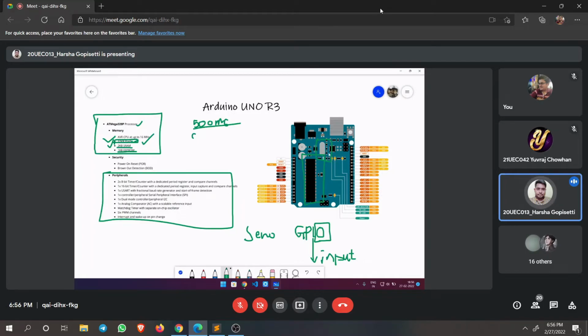For that, again we require this oscillator, which records the duration of the signal going to the distance and coming back. I mean, this two-way time is recorded, and we know that distance is equal to v times t. Here v will be the speed of sound, and this time will be half the total time, because we only require the one-way distance. If we take vt directly, we will get the two-way distance.